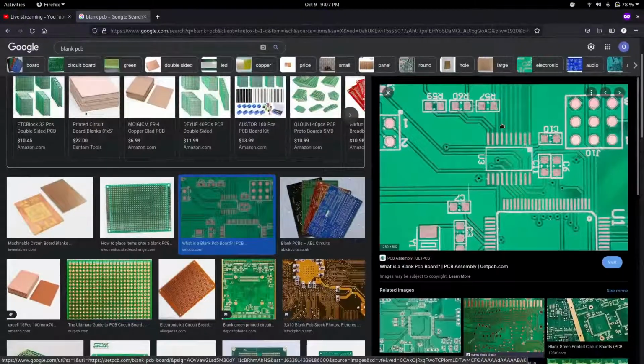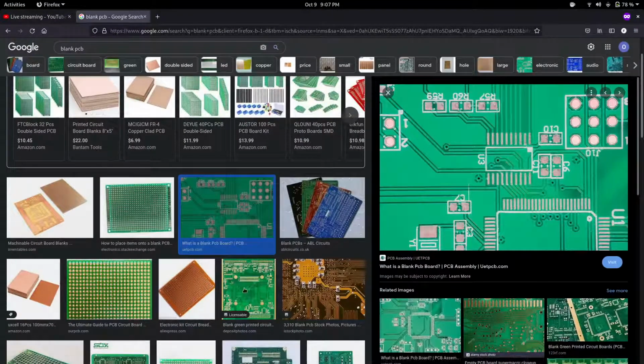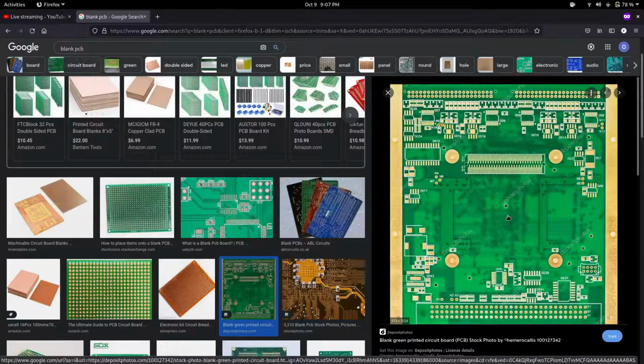Thanks. PCB design. There's a lot of stuff you can do with the actual properties of the design that changes its electrical characteristics. Also, and this is something you might encounter more often, there's the simple case of needing to do more than just interconnect. Suppose that you had a board that was designed to pass a lot of power. You would actually have to design some traces to be very thick so that they can pass more current. So, let's talk about the design flow for making a PCB.